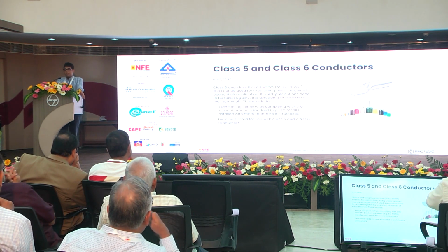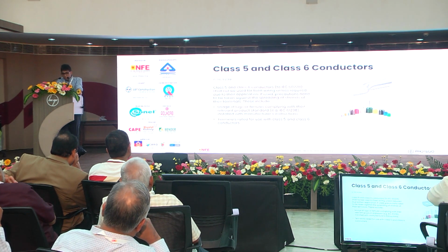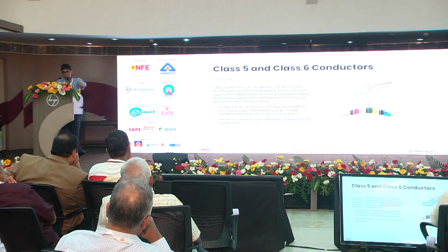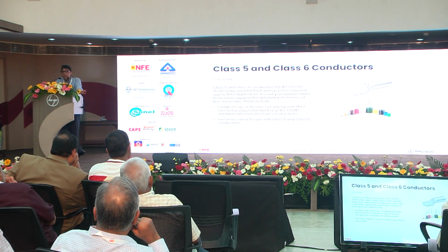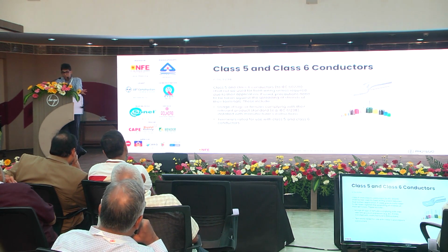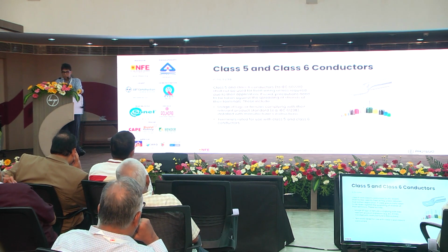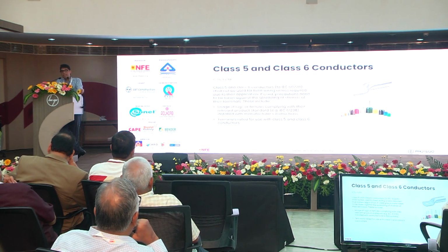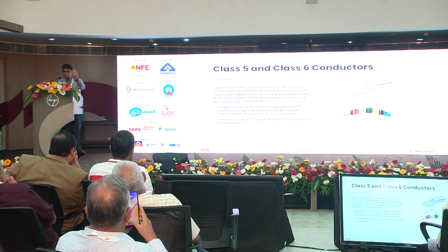Now, a very big thing in India is the use of class 5 conductors, class 6 not so much. See, which is your flexible cables, they shall not be used for fixed wiring unless they are required to, simply due to their application. And if they are used, you need to take precautions. One thing is you need to use a different current carrying capacity, like Mr. Gopakumar always says.